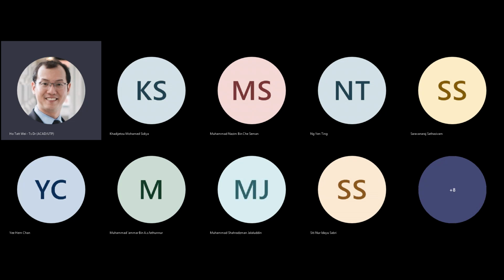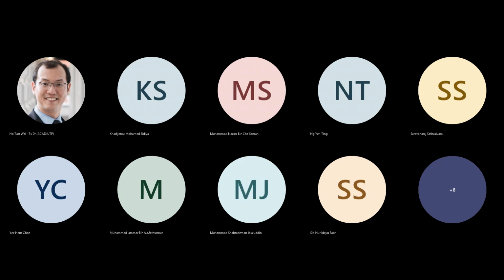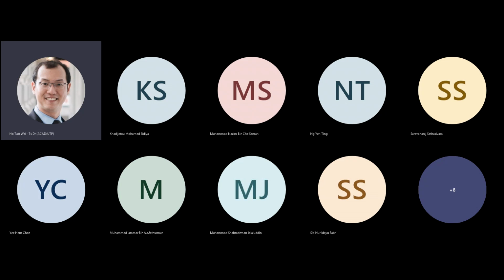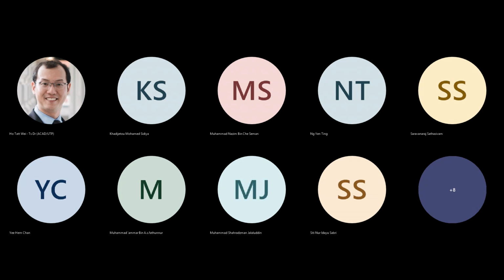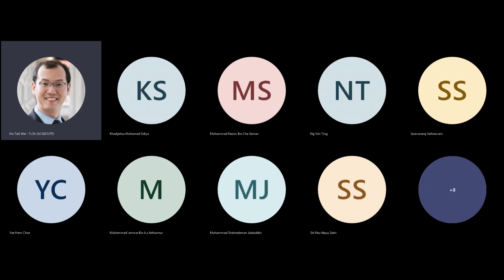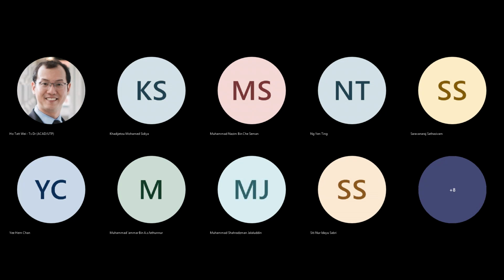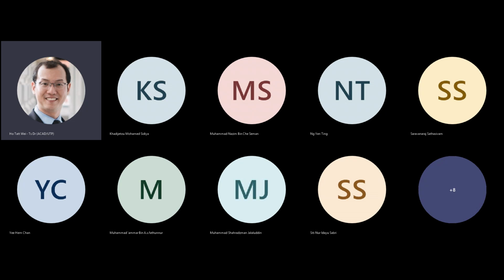But this is just an implementation of NMOS. And remember, we are implementing CMOS. So CMOS requires a complementary transistor here, as well as a complementary PMOS going through here, right? The drawing's pretty bad, so let me just draw it again. I'm basically connecting two transistors like this. And this is known as a pass gate, right?